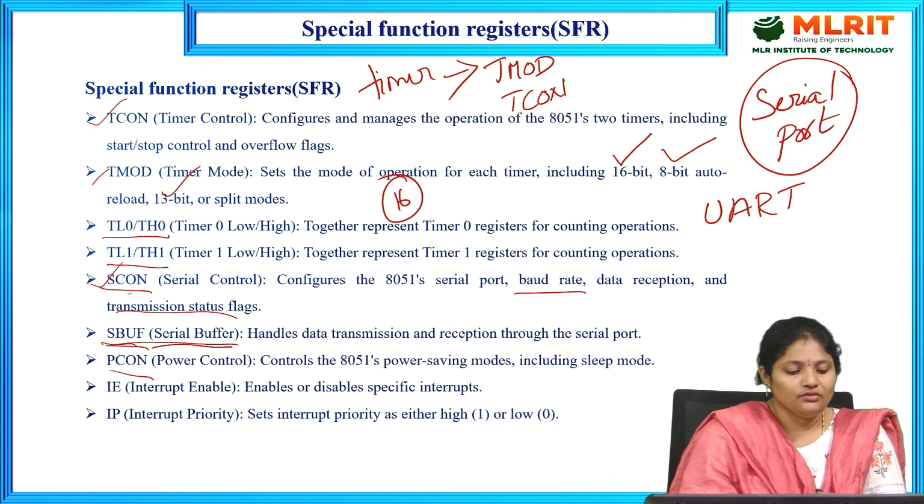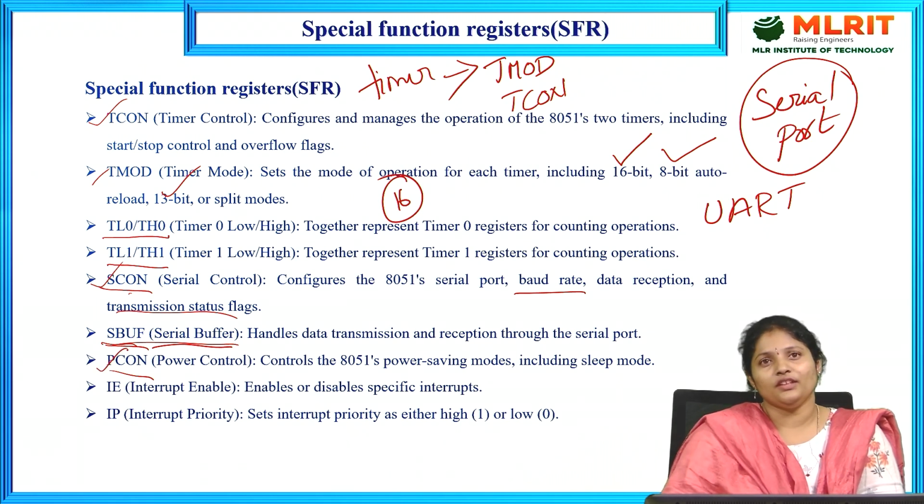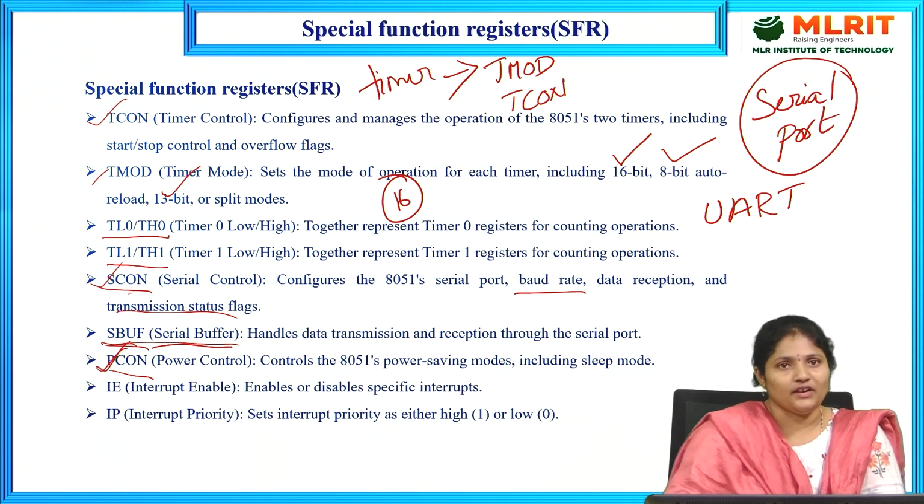Now coming to the PCON, as I already told you, the 8051 can be operated in idle mode and energy efficient mode. So to control the power of those modes, or to keep the microcontroller in the sleep mode, you can use this PCON special function register.